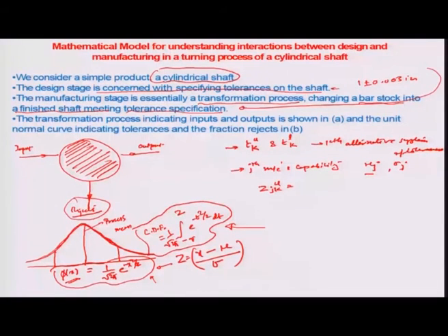cumulative distribution function, which is otherwise actually the scaled variable, if we look at here the CDF corresponding to the whole area under the curve varying from minus infinity to z equal to plus infinity happens to be unity. Okay. So, it is more like 100% of the parts qualify to lie within that distribution when we go from minus infinity to plus infinity of the scaled variable. So, the scaled variable in this particular case for overlaying the tolerance on our process capability for the jth machining system is given through an upper scaled variable and a lower scaled variable.